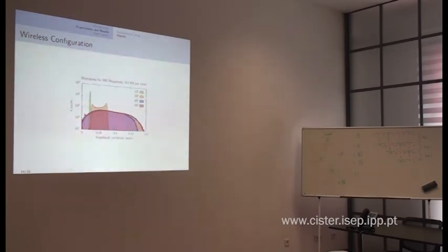This counts the number of observations versus the amplitude observed. With a single transmitter, we see a sharp peak with almost the same amplitude. If you have noise here, you still have enough signal to noise ratio, and you can decode the patterns.